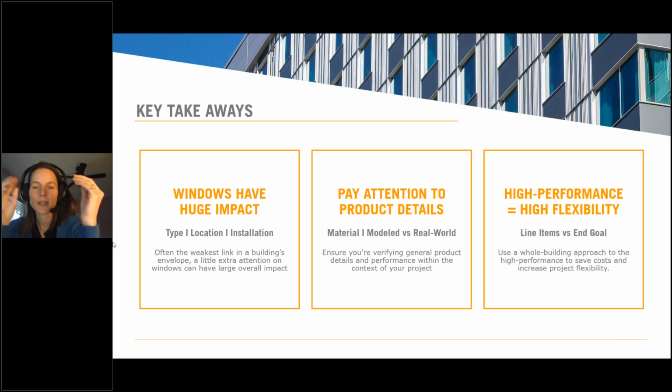At the point when you customize a window to accommodate the structural loads from a shading device, it basically destroys the thermal performance. You end up having to put steel and things inside the window. So it's better to avoid that if you can. But of course, there's customization that's possible.